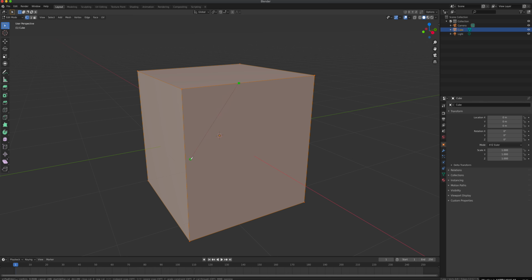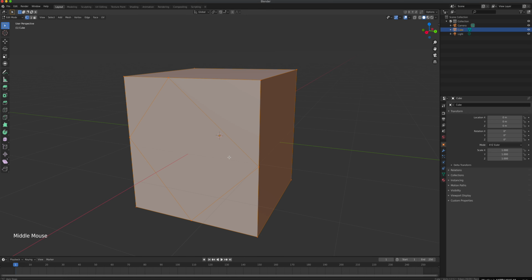So on this one, let's say I'm going to click here until it snaps. And then I click my mouse button again, and it still keeps going, as you can see right here. I'm going to create a diamond shape on the side of this cube, and I'm going to snap to that point. After that, it's still active. However, if I press enter right now, or return on a Mac, it stops the tool and then all those cuts become active. Okay, now I do have a cut right there.